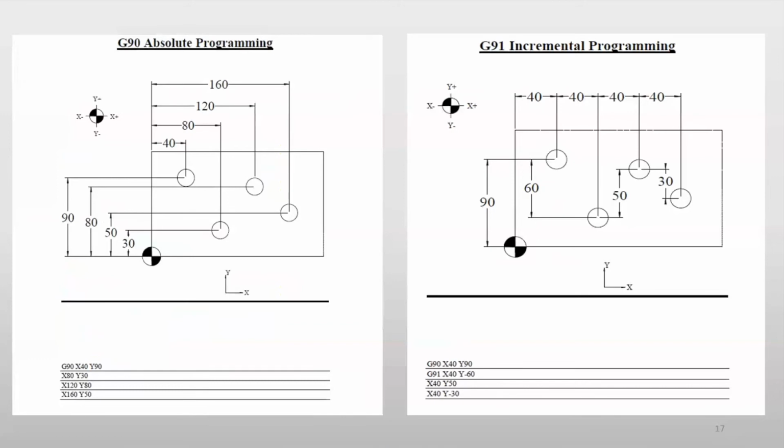The reason they went with that G90 program is because the amount of memory and RAM was quite expensive at the time. They couldn't hold this information, so the machine will always forget that. So that's why they use absolute programming. The majority of the codes are written in absolute programming. That's why even in post-processing, once you get the code, you can see it was G90 on the top.